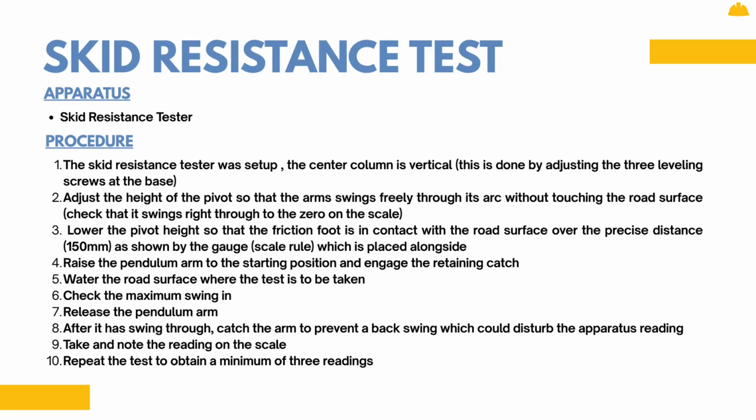Raise the pendulum arm to the starting position and lock it with a retaining catch. Now, wet the road surface at the exact spot where the test will be done. Check that the pendulum can swing fully and smoothly. Make sure there's no obstruction.